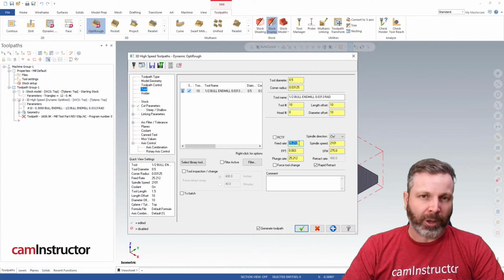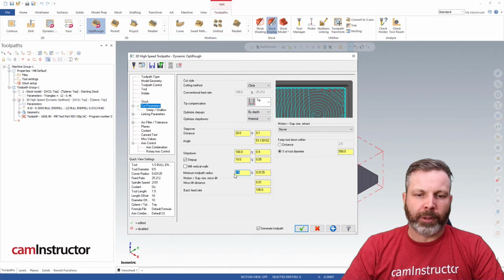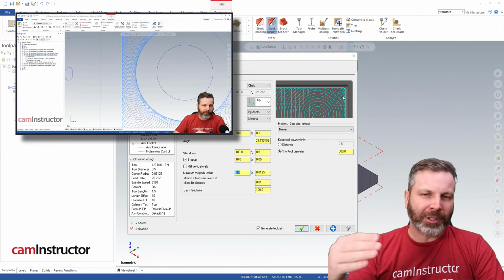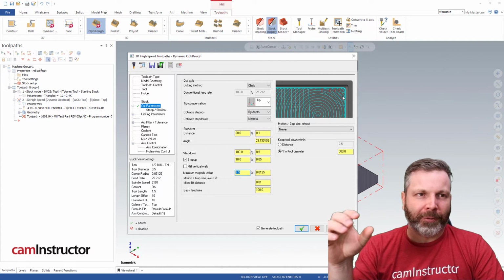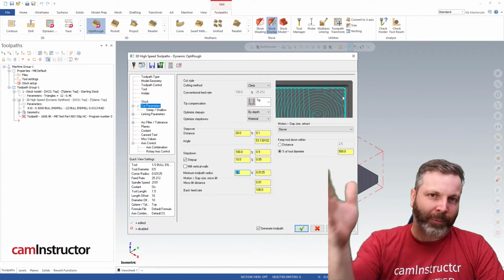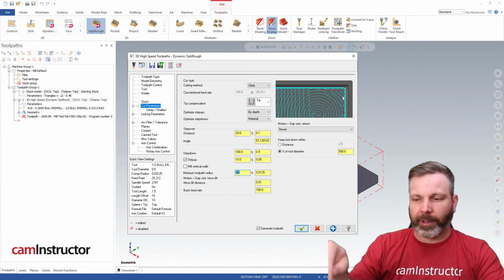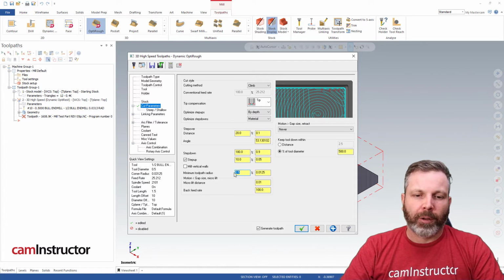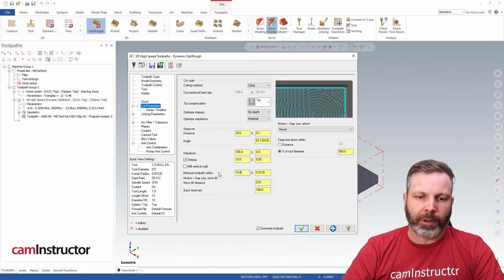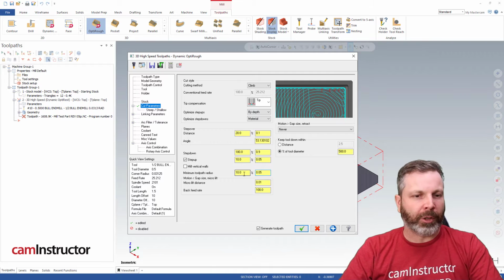This feed rate will be constant throughout the toolpath, and basically what can happen if you start making these really small arcs is your toolpath, again, I would suggest going and watching this video, the toolpath is making small circles, but the feed rate is still generated on the original feed rate. And that small circle, the outside of the cutter, is in fact moving faster than the middle of the cutter, and some problems can occur. So just be cautious when you're making extremely small values in here. When you have higher feed rates on your tools, it can cause problems and tool breakage.